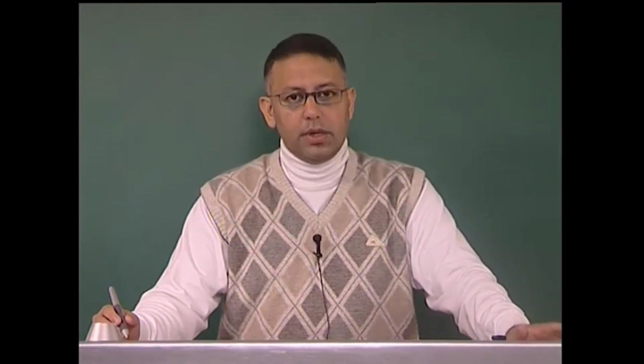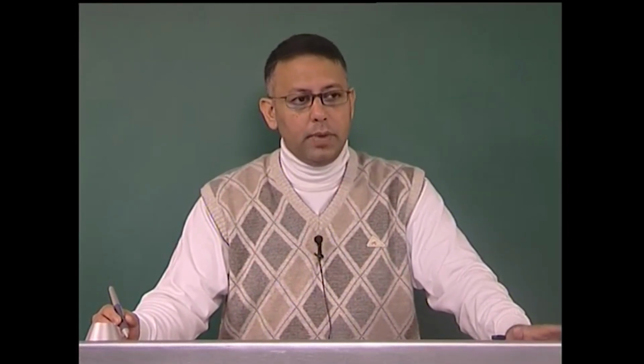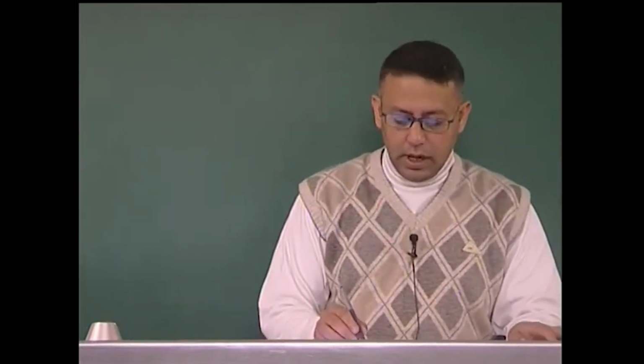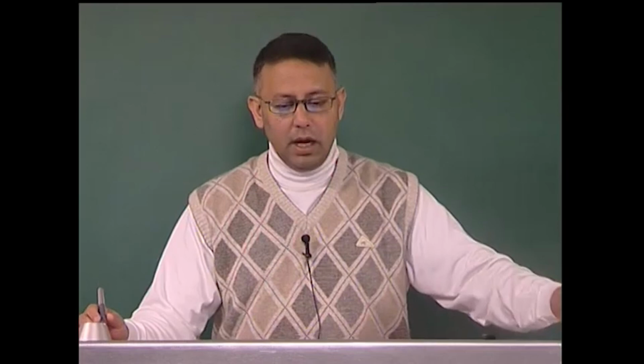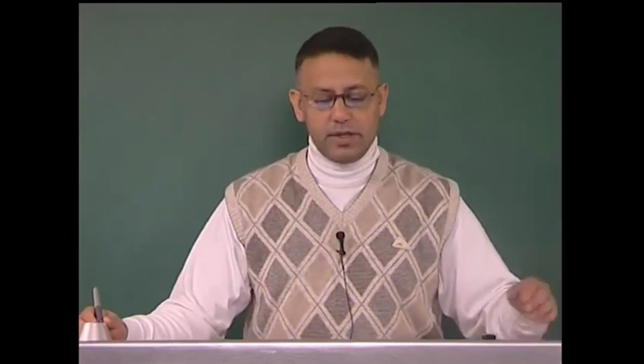So, let me summarize this slide. Number 1, residual stresses are important and they have to be considered within a functional framework of the definition of a microstructure. Number 2, residual stresses can be classified based on their occurrence on scale, which can be macro scale or micro scale, and all the other length scales which pervade between the scale of the vacancy or the atom to the scale of the entire component. They can arise because of various physical properties, like during a magnetic phase and you have a switching on of a magnetic field. They can arise from geometrical entities, and when I mean geometrical entities, I mean precipitates, etc.